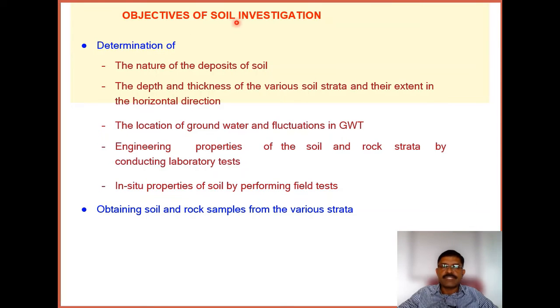The objectives of soil investigation: it is to determine the nature of the soil deposits. It is to find out the depth and thickness of various soil strata and their extent in the horizontal direction and in the vertical direction as well.